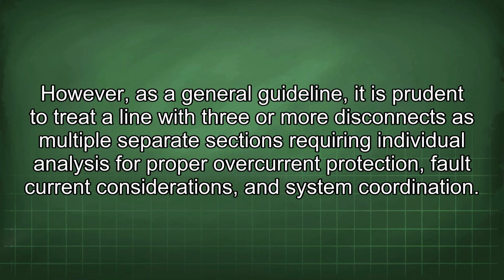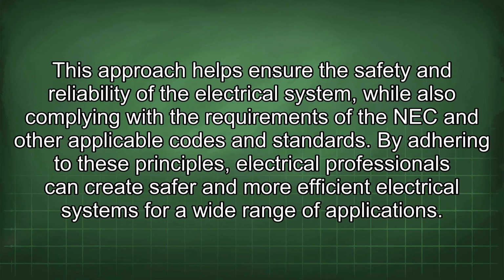However, as a general guideline, it is prudent to treat a line with 3 or more disconnects as multiple separate sections requiring individual analysis for proper overcurrent protection, fault current considerations, and system coordination. This approach helps ensure the safety and reliability of the electrical system while also complying with the requirements of the NEC and other applicable codes and standards. By adhering to these principles, electrical professionals can create safer and more efficient electrical systems for a wide range of applications.